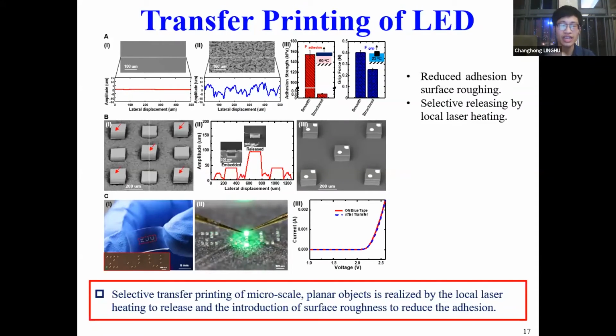So whenever the adhesion causes trouble, we can get rid of it simply by surface treatment or introducing some surface roughness. Here we introduce the surface roughness by molding the sandpaper, and it can be seen that the adhesion is reduced greatly, while the gripping force is not influenced obviously. This enables reliable gripping and release.